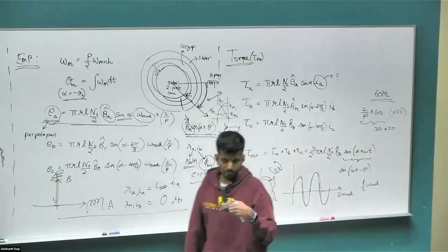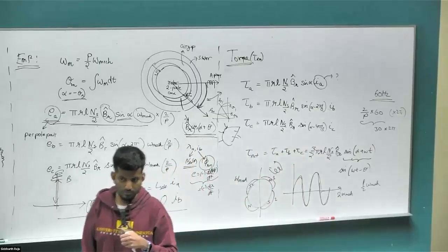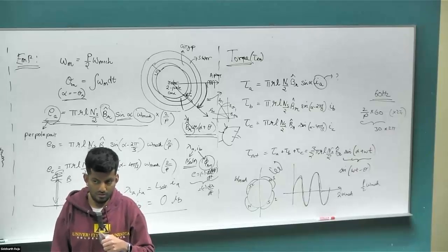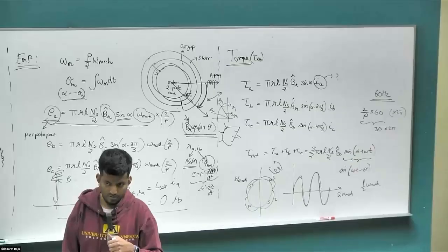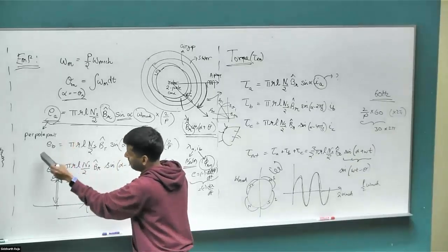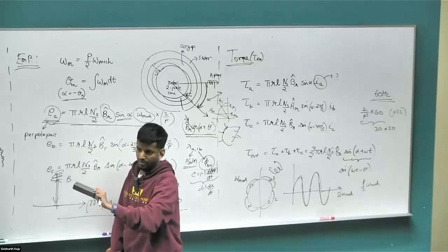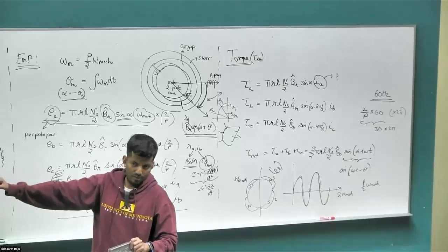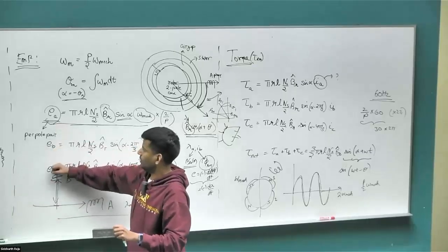When you're doing the series case, you multiply by the factor and then still add the EMF from B and the EMF from C? Or is it just for EA that you multiply by the additional factor? Just for the EA. You don't add these EA, EB, EC together, right? Because those are 3 separate voltage sources that are present in an equivalent circuit. These are completely independent 3 voltage sources.